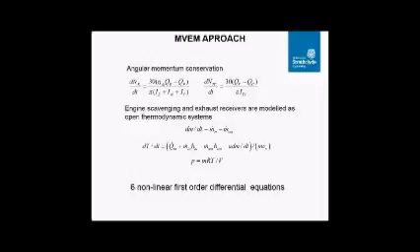the torque of the engine, of the propeller, of the turbine, and of the compressor. With the I, we represent the polar moments of inertia of the engine, the shafting system, the propeller, and the turbocharger shaft. And with the small n, we represent the efficiency of the shafting system.